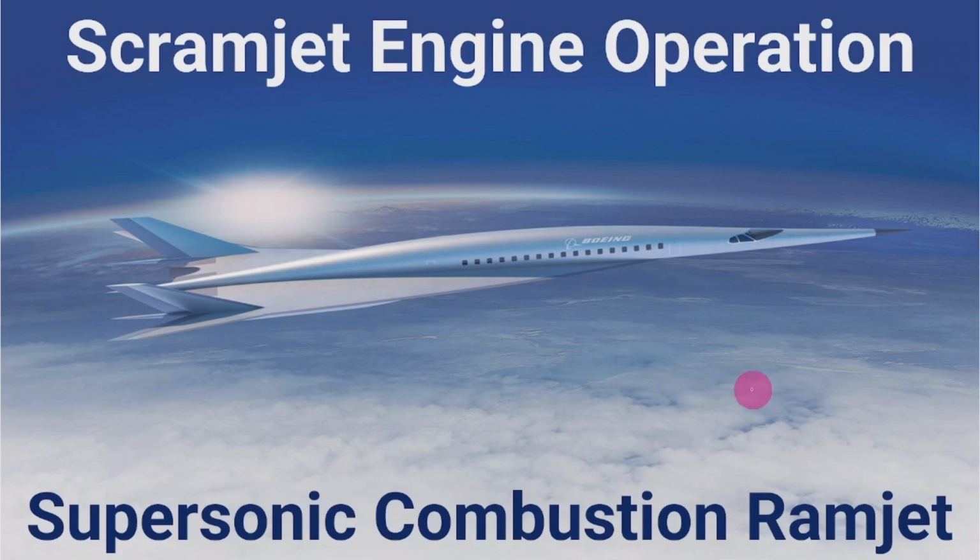In that, the combustion is taking place at the supersonic speed of the air. That is the scramjet engine. It is a specific technology where air enters at supersonic speed and combustion takes place at the supersonic speed, and the exhaust gas is also coming at supersonic speed, which is at a speed of Mach more than 5.